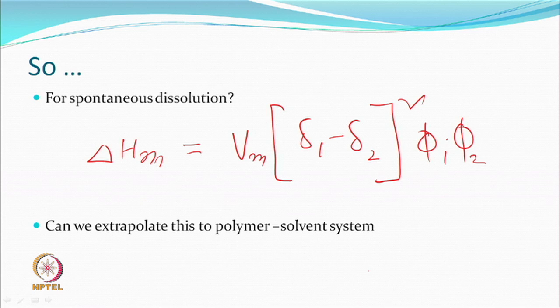Solute versus solvent, or solvent versus solvent, is a very different situation than a polymer. A polymer is a long molecule, and if you look at a polymer like textile, you have a semi-crystalline material. So, diffusion in the amorphous region can take place relatively easily. It will take more time to get into the crystalline region.